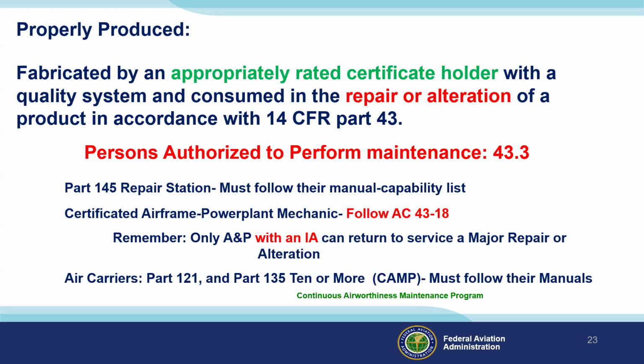Certificated A&P mechanic, they would probably follow AC 43-18. And keep in mind that only an A&P with an IA, inspection authorization, can return to service a major repair or major alteration. And air carriers can also perform maintenance.